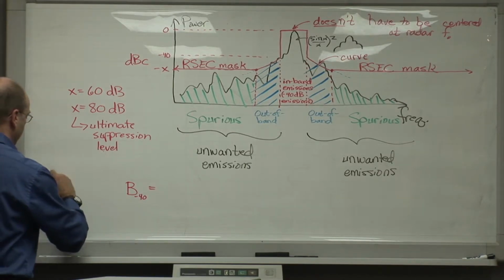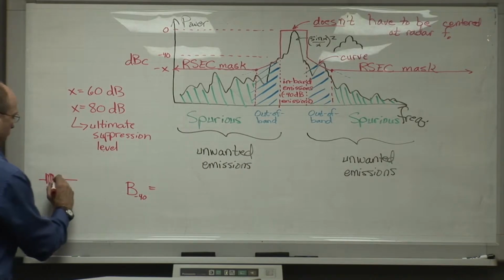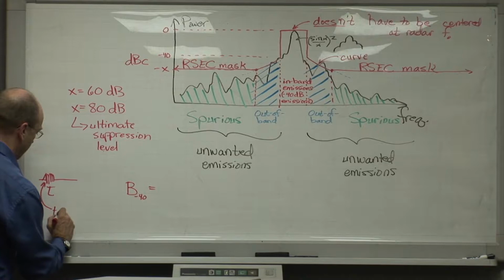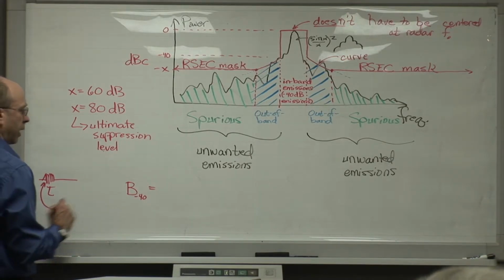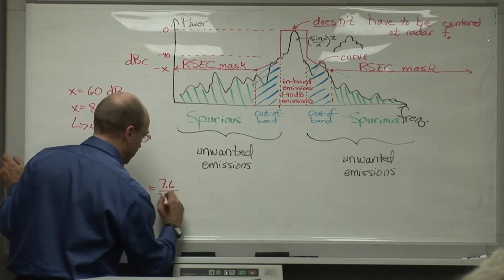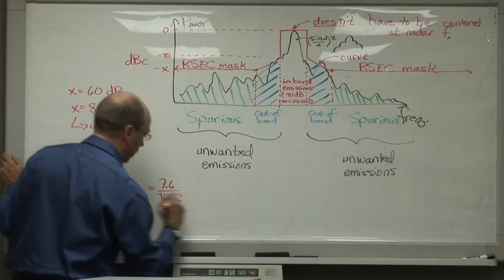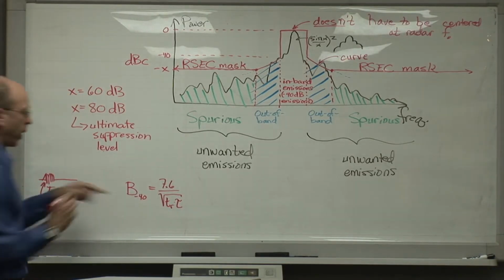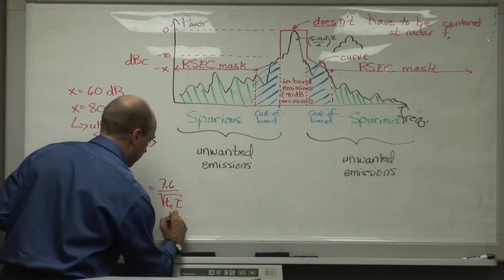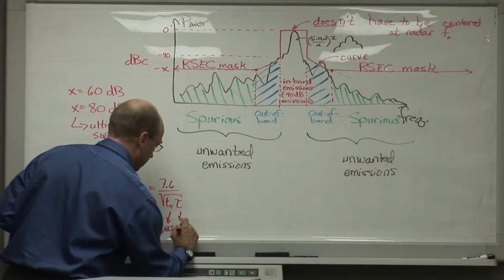That is a radar which transmits pulses with some pulse width tau, which have some short rise time, t sub r, is 7.6 divided by the square root of the rise time multiplied by the pulse width tau, where the units of the 40 dB bandwidth are megahertz, and the units of t sub r and tau are microseconds.